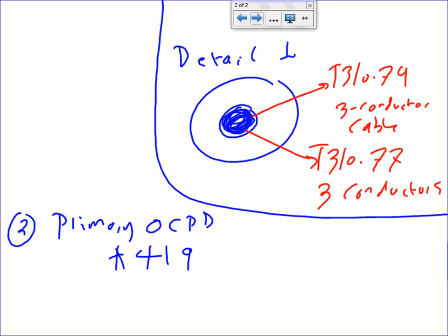And Ryan, what's the multiplier from the table? Anybody can give me the multiplier from table 450.3(B)? You're in a circuit breaker? Fuse. We're using a fuse. 300. So that will get you 1200 something. Anybody has a calculator? 1257. How much? 1257.